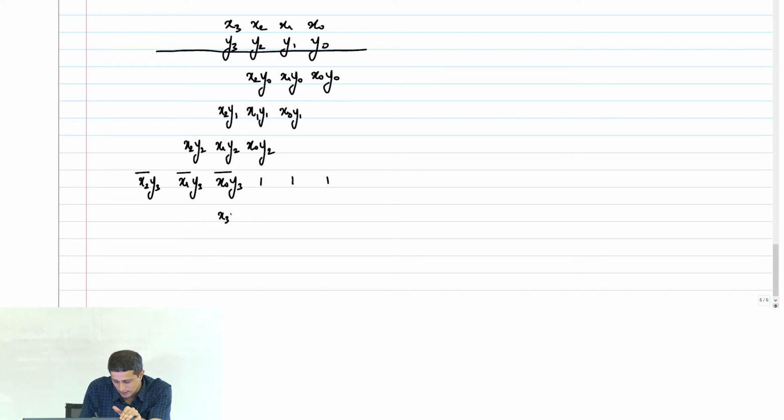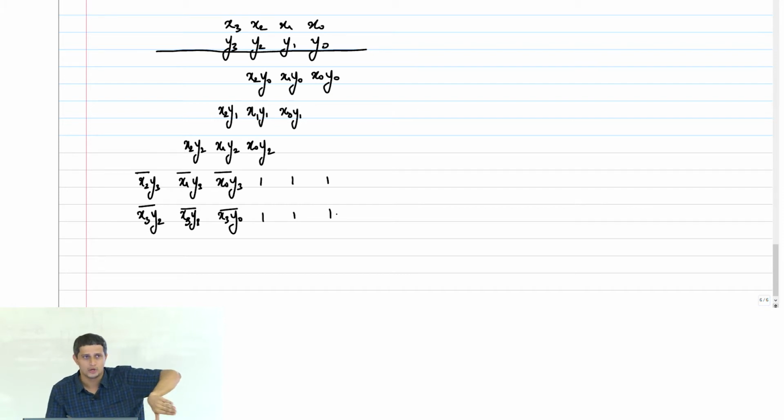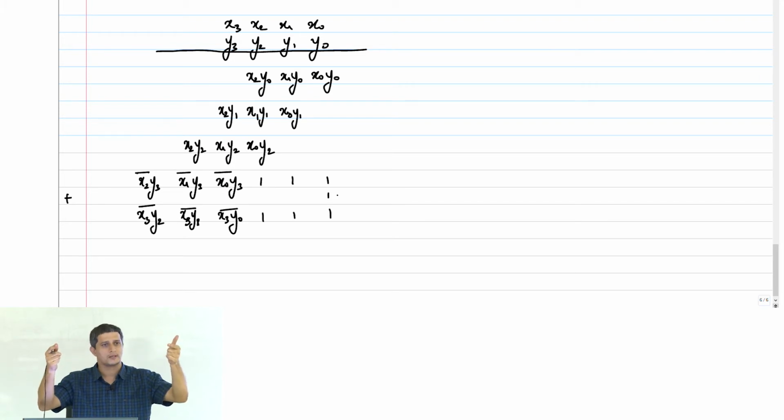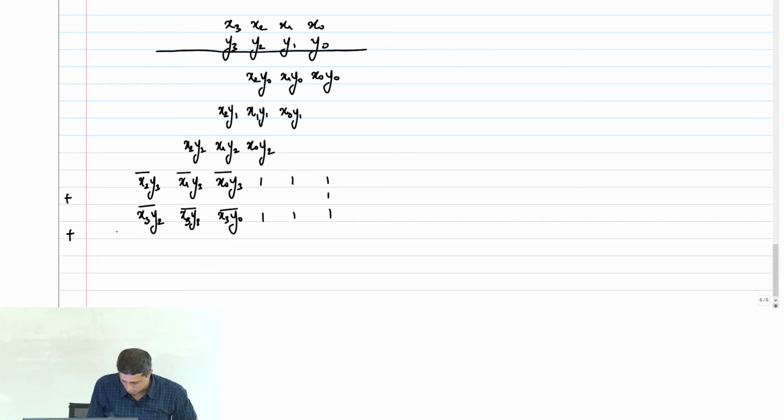These are x3y0, x3y1 and x3y2. That's also a negative number, so I will invert that also. This is 1, 1, 1. I am not putting the ones on the left yet because we don't know how many bits we need. We'll come to that. And then what should I do? I need to add a 1, because you invert every bit and then add a 1. That's how you get the 2's complement number. That's what I want to do here.